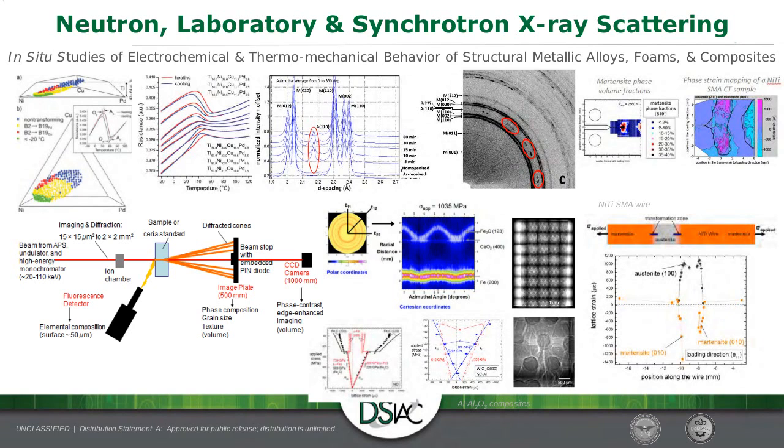And we are looking at, I showed just one, but we were looking at applying it to copper-based alloys, iron-based alloys. So it's a mechanism effect and not a material-dependent effect. So as long as it has shape memory, we're able to do that. And that opens the door to other materials and other applications.